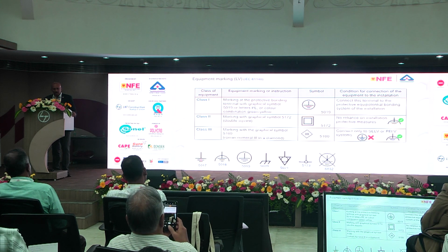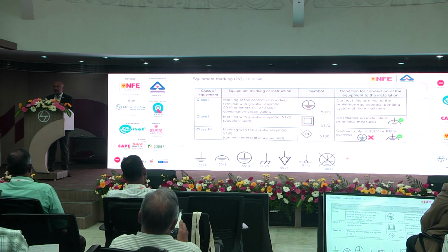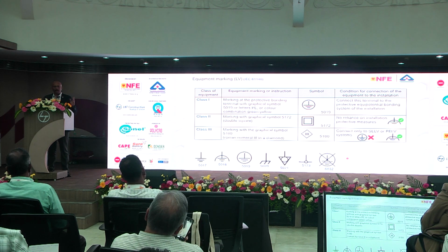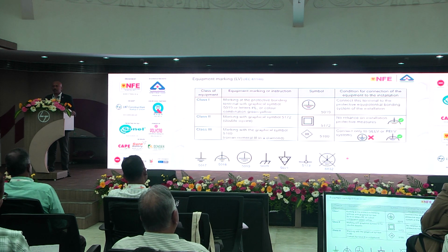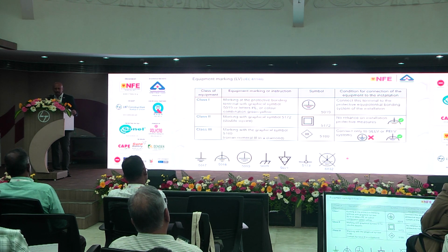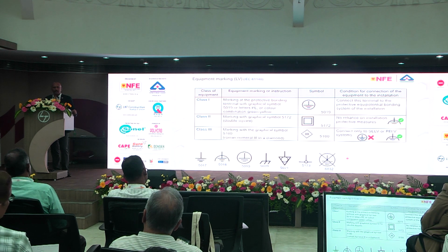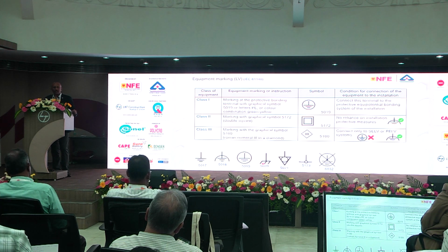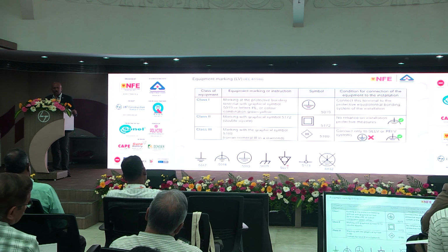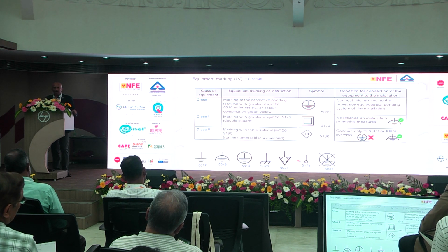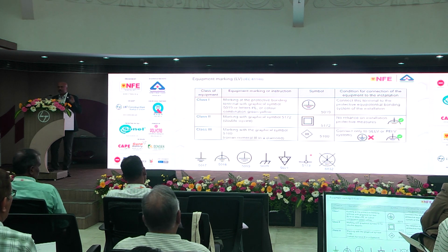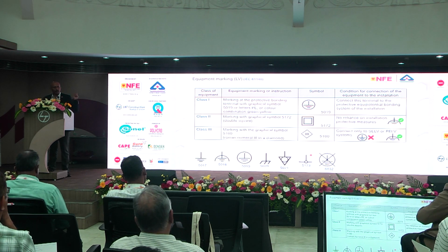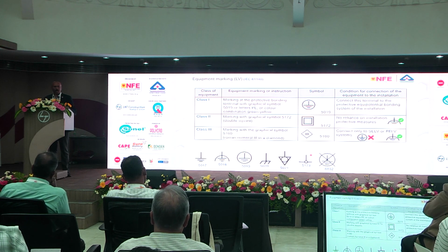Now at the bottom I have put a lot of symbols: 5017, 18, 19, 20, 21. These are the symbols of earthing which are applicable for different applications. All are related to earthing. The first one, 5017, is the generic symbol. 5018 is called functional earthing. 5019 is safety earthing or protective earthing. 5020 is called functional bonding or chassis earthing. 5021 is called chassis equipotentiality. Then there is earth terminal potential closer to the functional earthing, and no protective earthing. These are the symbols which are used in the apparatus. So you should make the earthing appropriately according to the meaning. It is not like you take a wire and interconnect everywhere.